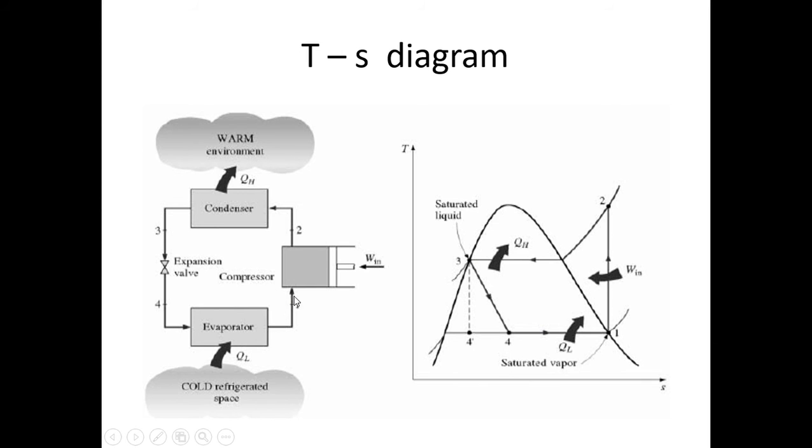So compressor, point 1, you have a saturated vapor entering into this compressor at lower pressure, that is suction pressure. This is a saturation point on this curve. From here compression 1-2 is an isentropic process, which means entropy should be constant. It's a constant entropy vertical line from this suction pressure to delivery pressure. So 1-2 will be a vertical straight line like this.